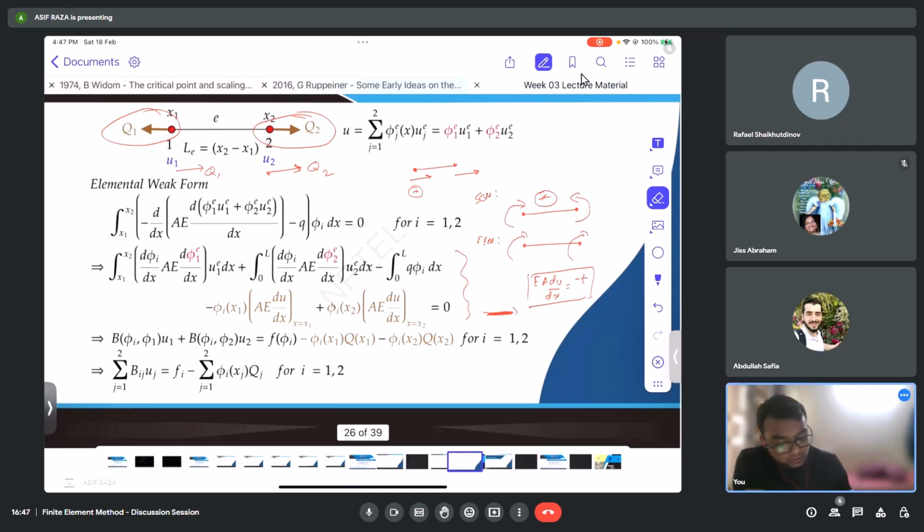Yes, actually this is the traction itself, like in the boundary condition. When you are provided with the governing equation in the strong form, what do you have? Governing equation and boundary conditions. For a bar problem, one boundary condition would be a Dirichlet boundary condition and one would be a Neumann or natural boundary condition.